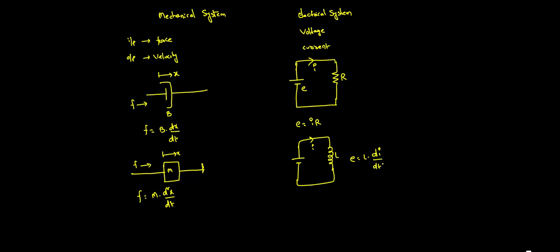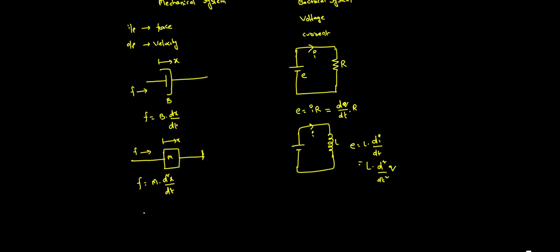So how do you see this? Here dx by dt is coming directly as I. If I write I equal to dq by dt, here also, it will become d square by dt square into q. So the equations are very clear in terms of how the system is being represented. For the spring, the force that we are giving onto the spring, assuming it is fixed at a reference and displaced by x, is F. So F is equal to k into x.